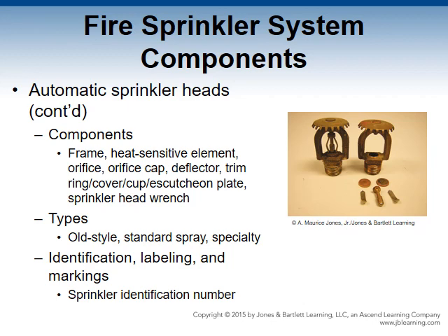Early suppression fast response sprinkler heads, known as ESFR, discharge a great amount of water to penetrate strong updrafts and are designed to suppress a fire, not just control it. You also have large droplet sprinkler heads, which may be seen in facilities, but few manufacturers still produce them, and NFPA 13 no longer discusses them.